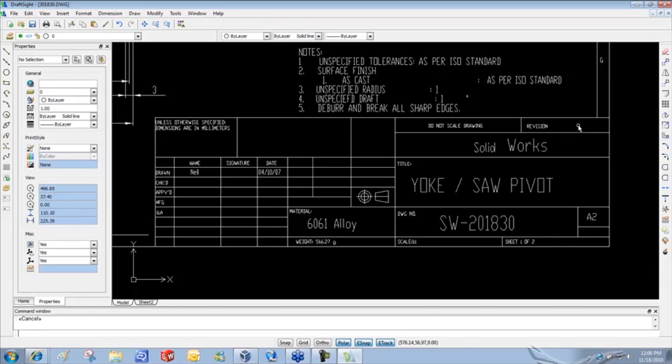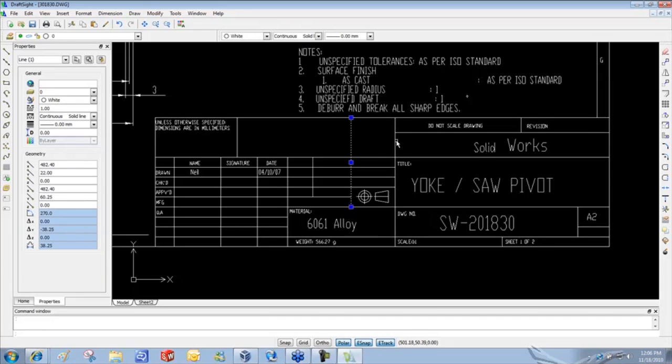Now the way that this drawing is set up right now, these are all just lines. You know, I could select them individually as well as notes, right? So this is just a standard AutoCAD DWG type note here. And that's fine if you're not trying to extract information from the file, but if you do want to extract information from the file, you have to turn these into what the DWG community calls blocks.